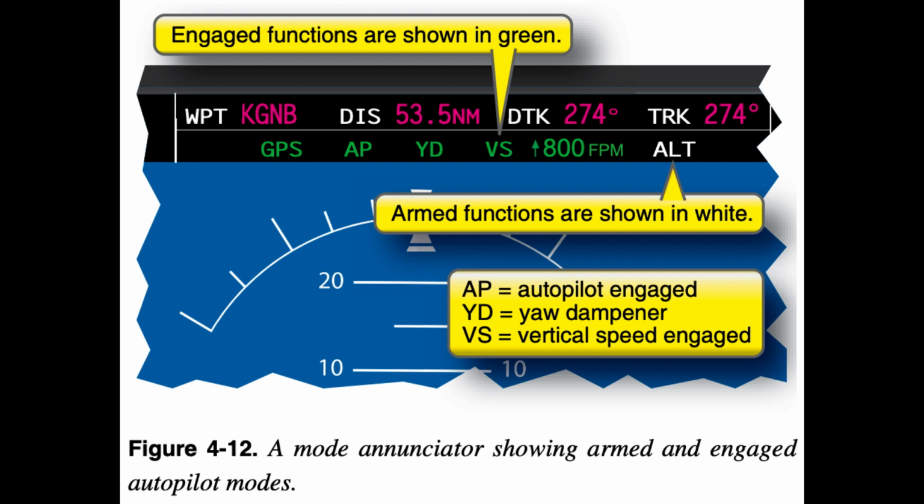Awareness, altitude alerting systems. Altitude alerting systems were mandated for commercial jet transports in the early 1970s in response to a growing number of altitude deviations in airline operations. Although they helped reduce the total number of altitude deviations, altitude alerting systems also made possible a new kind of error. Altitude deviation reports submitted to the Aviation Safety and Reporting System (ASRS) indicate that pilots sometimes rely too much on the altitude alerting system, using it as a substitute for maintaining altitude awareness.